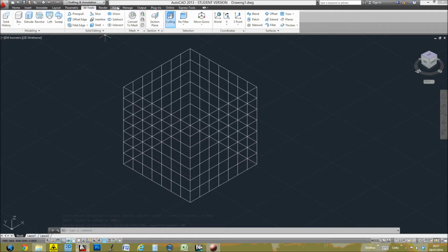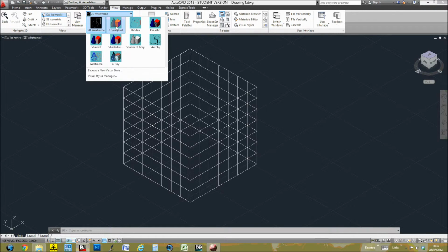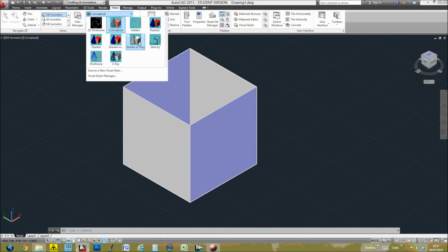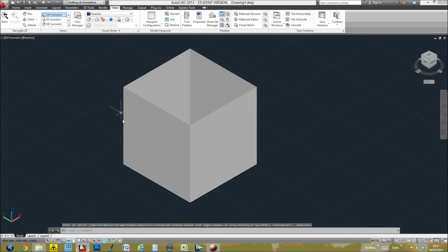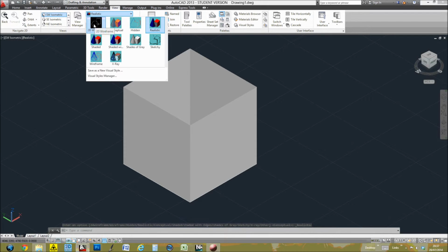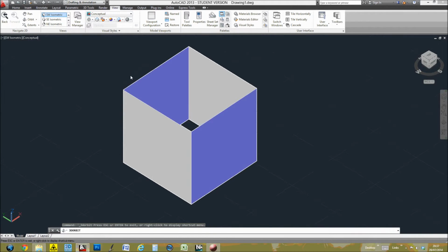If I go into my view command, at the moment we're on wireframe, I can click this to something more like conceptual, and I can even click on a range of different options here. So if I click on realistic, it will try and render it out and make it more realistic. I tend to like to work in either 2D wireframe or conceptual views though. If you click on the orbit button here and left click and move the mouse around, you can...